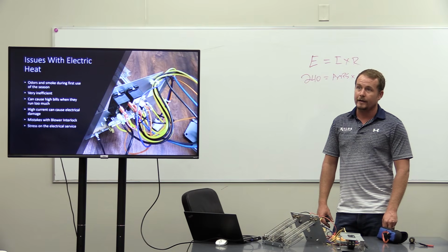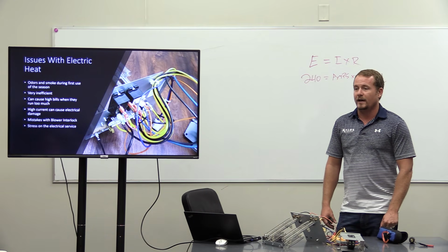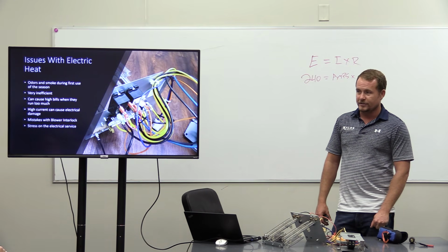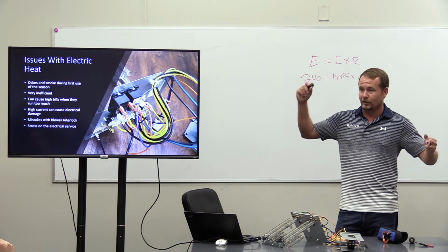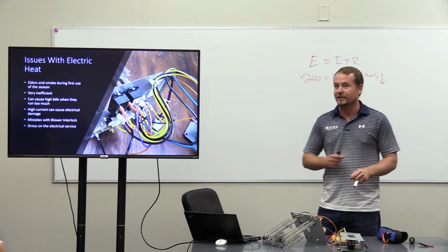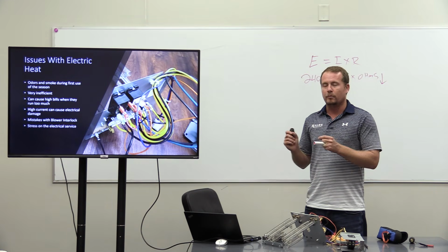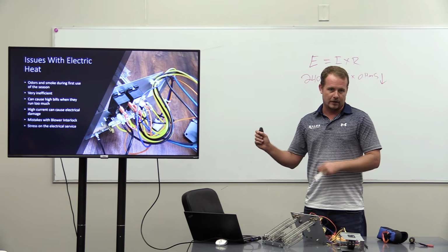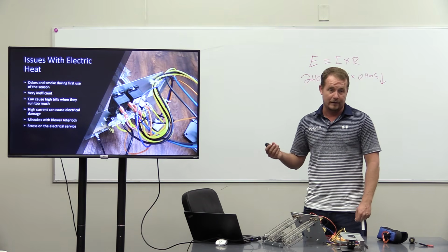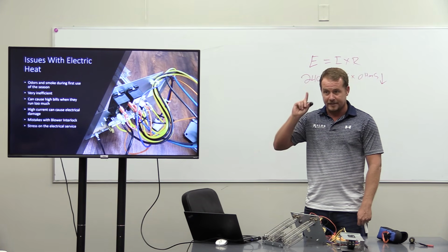I've seen it, yeah. And again, we're not qualified to do electrical load calculations because it's not just as easy as just adding all the loads up. It's not like that. There's a whole formula. There's a whole sheet that you have to fill out in order to do that. The point just being that if you go to a house that has a 100 amp service on it, or even 125, and you're pulling a furnace out, stop.